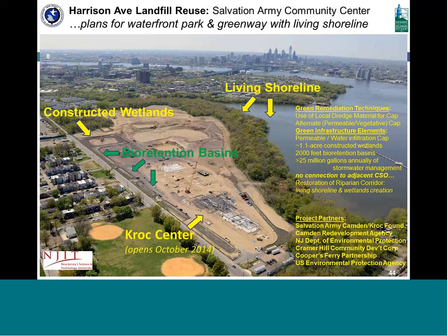But working on the Kroc Center since 2006 presented an opportunity to do things a different way in the city of Camden, working with our local partners, of course. And you can see there's green remediation elements on that part of the Harrison Avenue landfill. There are 2,000 feet of bioretention basins, over 1 acre constructed wetland, all these things to maintain stormwater on the site so we don't add to the combined sewer system problem that we have in the city of Camden.